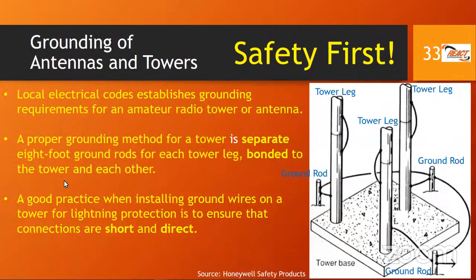All right, so we come to grounding again as a topic, right? So grounding is very important in amateur radio. So there are electrical codes that require grounding. So you might have heard of the NEC in Trinidad and Tobago. There's also electrical code, and it specifies that you need to ground certain things, right? So your amateur radio station will be guided in terms of the grounding by the local electrical codes that will determine what the appropriate grounding is for your antenna or your tower.